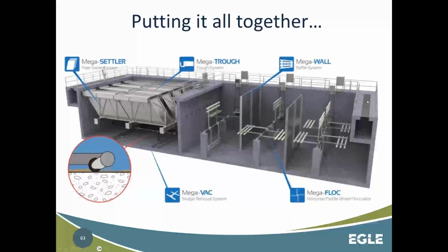Here, I think this is something that is also pretty common. It's almost like the opposite of a weir in a sense, but the water comes in and you can see there's all these little holes drilled into this trough. And that's basically just making sure that the water gets evenly distributed across the entire length of the basin, and that we're not ending up with all of it just dropping out at the first end and having a big dead zone over here. They do the same thing on this side.